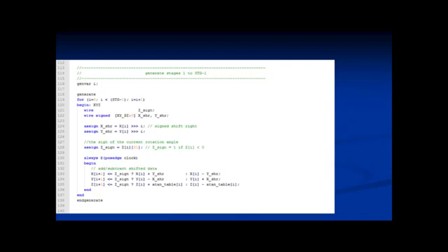Let's go through the logic. First, we have a 1-bit wide variable called z_sign. This too is replicated 15 times, one for each stage of the pipeline. Think of each stage as a block of code that is connected to the next stage in a certain manner. Next, variables x_shr and y_shr, or x shift right and y shift right, are declared for each stage in line 122. Lines 124 and 125 define how they are calculated. Notice they are assigned values, and the number of bits they are shifted right depends on what stage they are at.